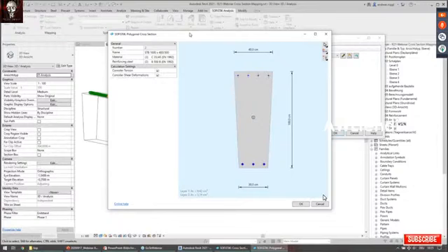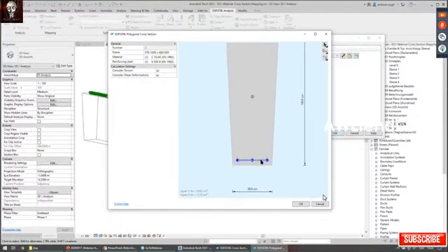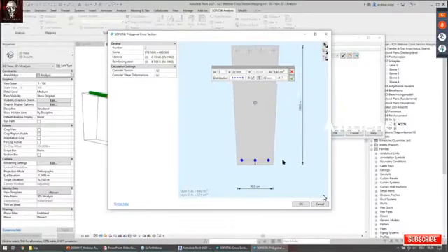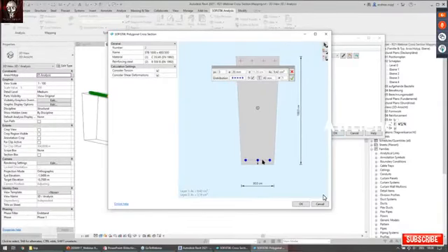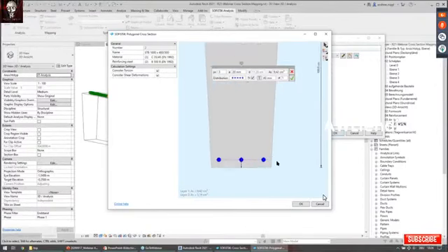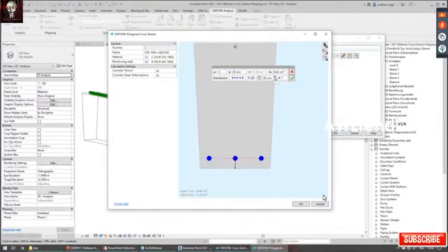And now with this new dialog, which comes with version 2021, you can further configure this section. You will see that I can just modify the already given rebar. By default, we are just creating 2 layers of rebar at the upper and lower side. But you could also delete that rebar and reconfigure it again. And here you can configure it. For example, you can change the distance to the boundaries, or the number of bars being used, or the diameter, and other properties as well.